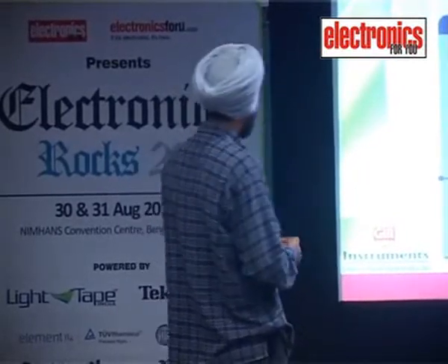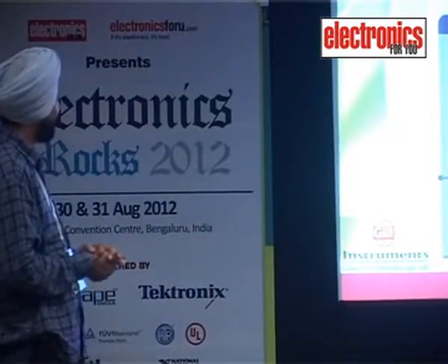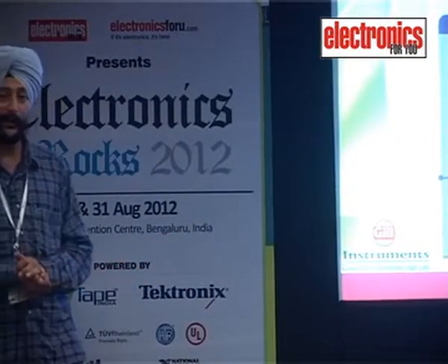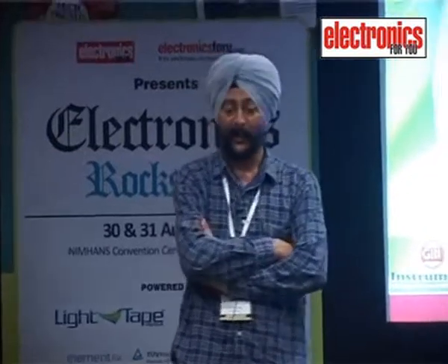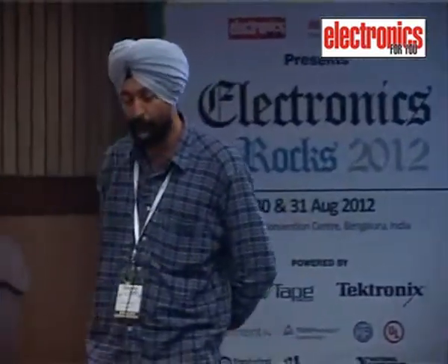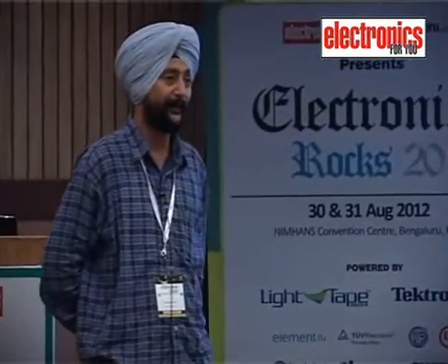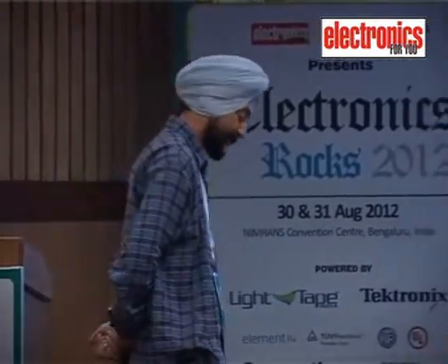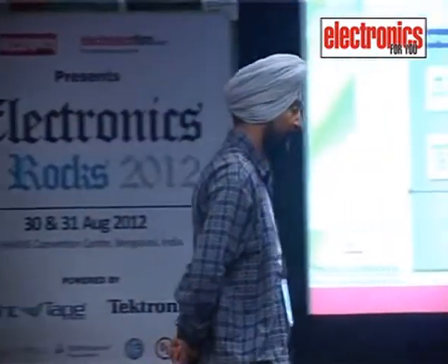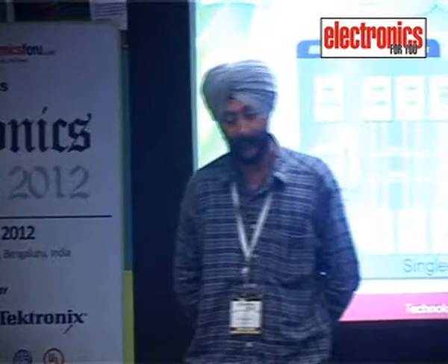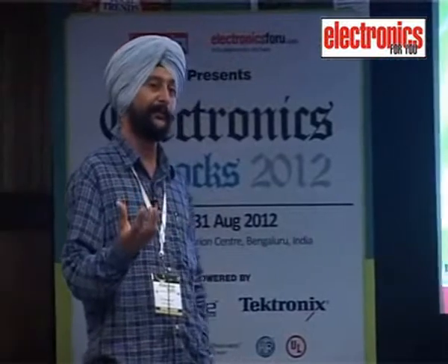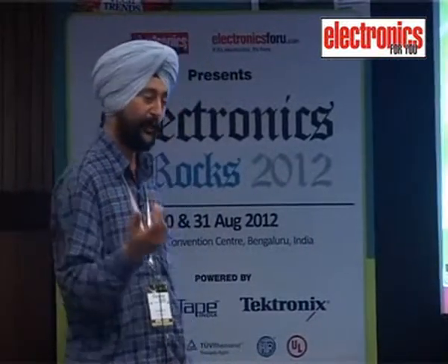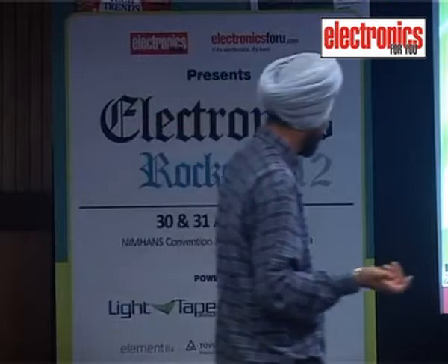And if you look at the kind of memories we have available nowadays, you have a huge on-chip flash memory. You have RAM up to 16 kilobytes. Actually, as you know, MSP 430 is a family. Today we have more than 450 devices. The flavors are available from the MSP 430 family. Everywhere you have the same 16-bit CPU, but with different peripherals and different memory capacity for different applications. Some dedicated chipsets are even available, with ASICs for energy meter, flow meter, water meter, gas meter, right?